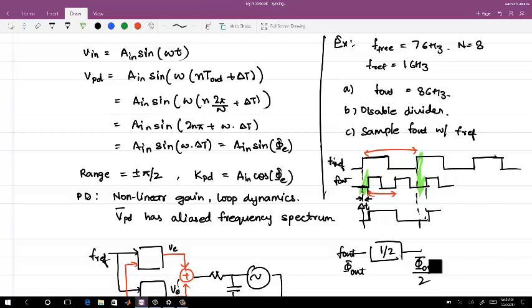Even in that case, you will need some way to check whether the frequency of the oscillator drifts, because this sample phase error detection will not work if the frequency drifts beyond a certain point. So there will be some kind of periodic check, some kind of compensation which brings the frequency back over a period of time. That will be there.